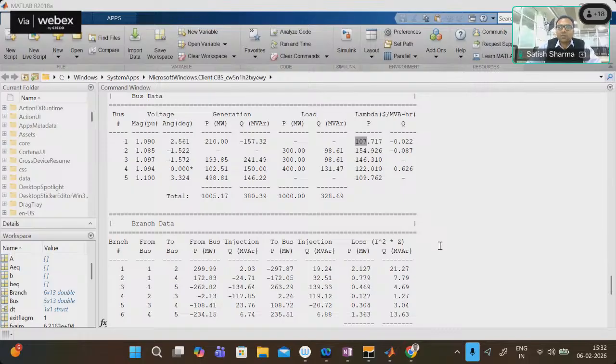Dynamic OPF is something else. When for the entire 24 hours we are solving the optimal power flow, we call it dynamic OPF, not dynamics of OPF. Dynamic OPF is like time dependent OPF, and still it is a steady state problem. It's not at all a dynamics problem, because for a time period we assume that everything is at steady state. We assume either a 15-minute, 30-minute or 1 hour interval, and for those 15 minutes we assume that the load is constant. Here in this particular problem, we consider that load is fixed and does not change with respect to time.